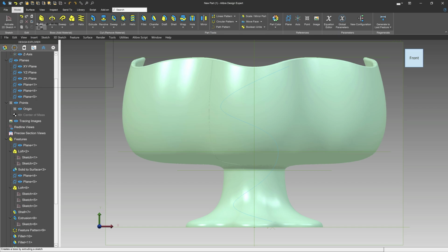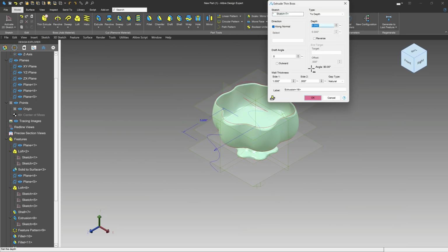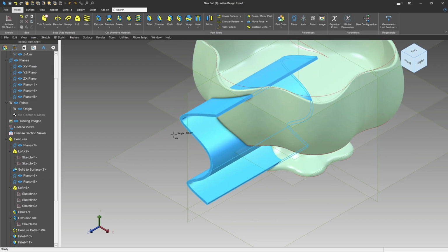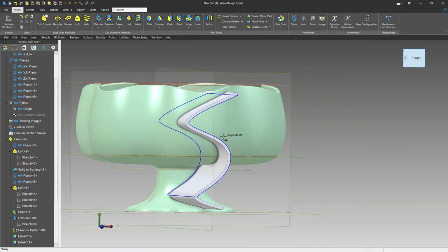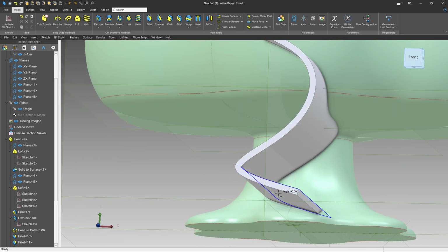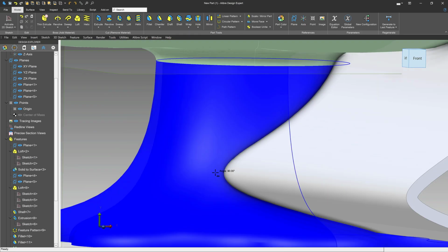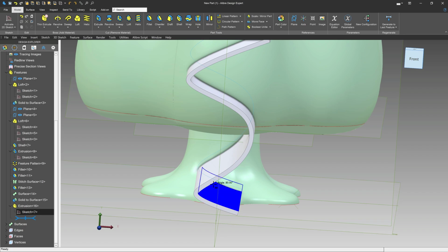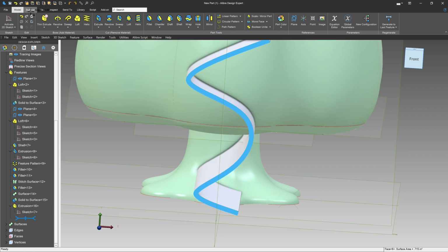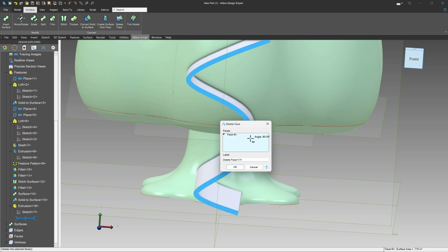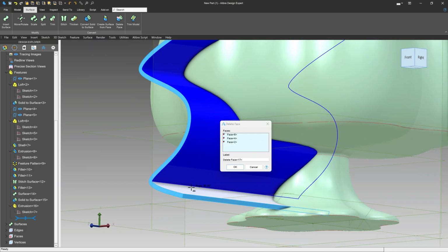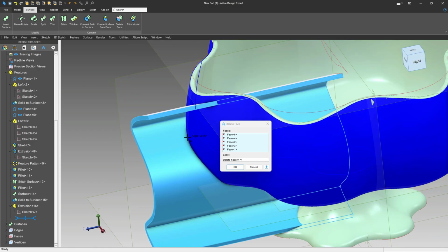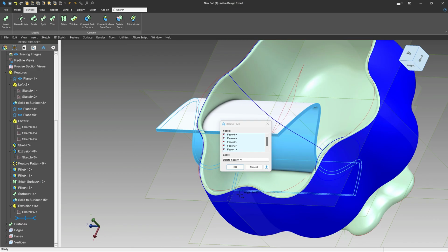So we'll deactivate that, and I'm going to thin extrude. And I can take down my wall thickness a little bit. And of course, I care only about one face of all of these faces. That's going to be the face that's connected with my sketch. Right. So that's going to be this face right here. Every other face I'm going to select on the Surface tab and click on Delete Face. Just like that. We'll say OK.